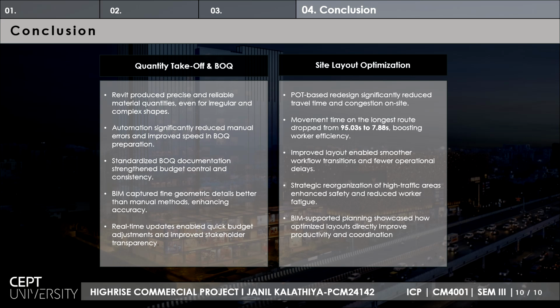At different phases this could be checked from the Revit model by following the quantity takeoff procedure. Also, a BOQ can be generated very easily as per the elements and materials that will be used in the construction process. BOQ can be generated pretty effectively. Also, in quantity takeoff, a precise quantity is given by Revit, which gives better efficiency.